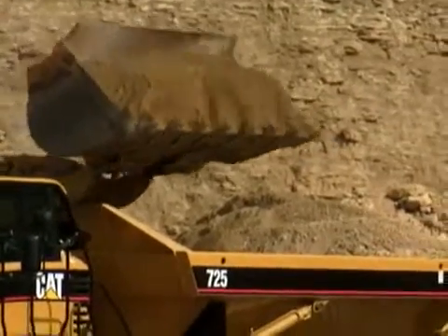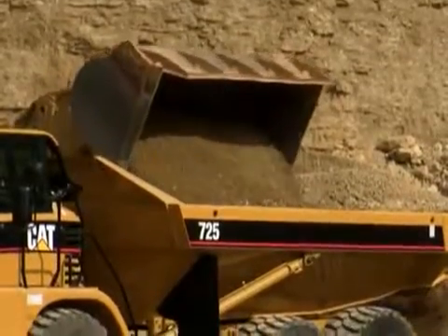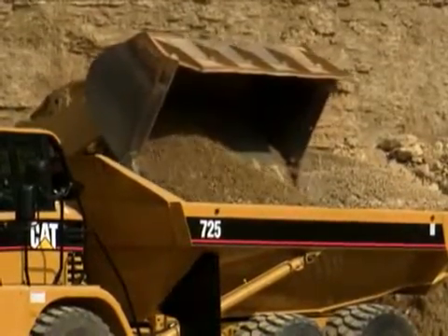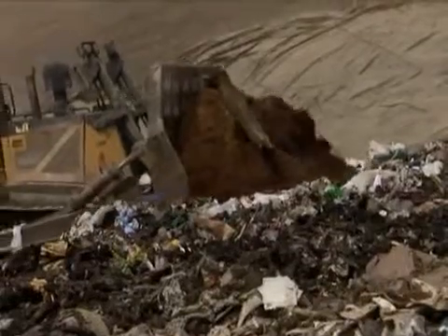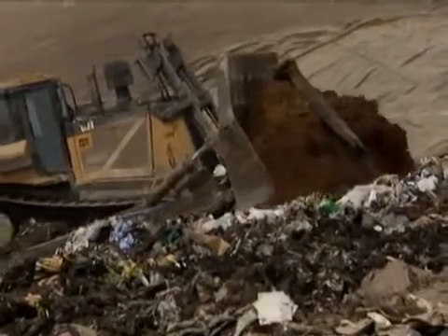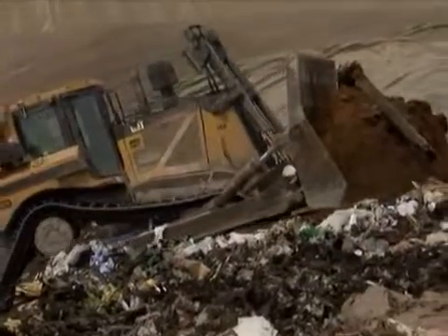In fuel systems, clearances are smaller, as small as 2 microns. This inside view of a 3500B injector tip shows how very small contaminants have clogged 4 of the 8 orifices, restricting proper fuel injection and causing loss of power. Dirty fuel is the largest cause of fuel system failure.